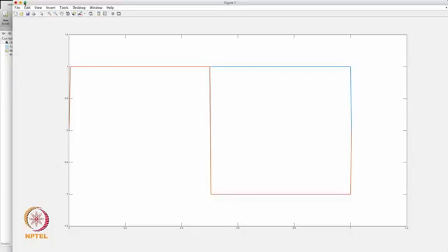Very often one has difficulty in visualizing how these functions, whether phi of t or psi of t, look when they are scaled and translated, either dilated or compressed. Normally we are interested in the dilated versions, because as we have learnt earlier, the signal is available at the finest time resolution, and we always end up constructing only approximations, and approximations are generated by the dilated version.